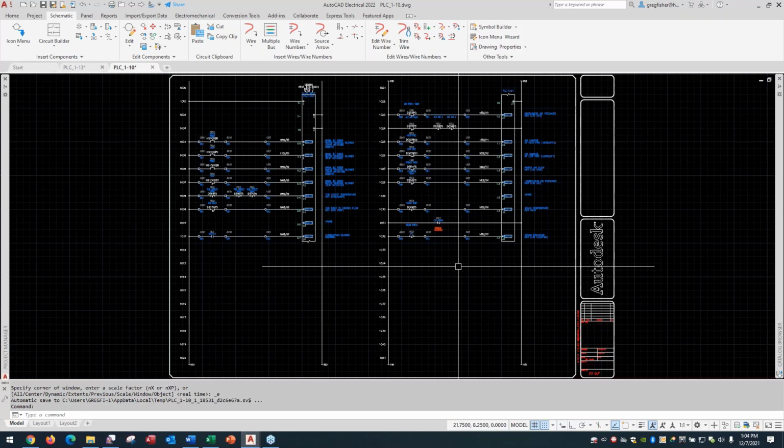Yep. So Nathan had kind of a follow-up, and you and I both thought about this. If you've got an illuminated push button, the push button itself is the input, the light is an output. Can that be done? If it's a parent-child relationship, then sure. You put the parent that goes to the input, and then the child symbol that represents the output.